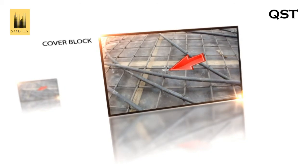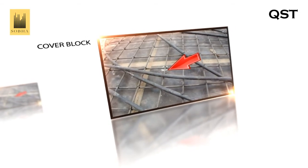Cover block should be made of cement mortar 1:2 and it must be used after 7 days of curing. It is mainly used to ensure that the reinforcement is completely embedded in concrete.